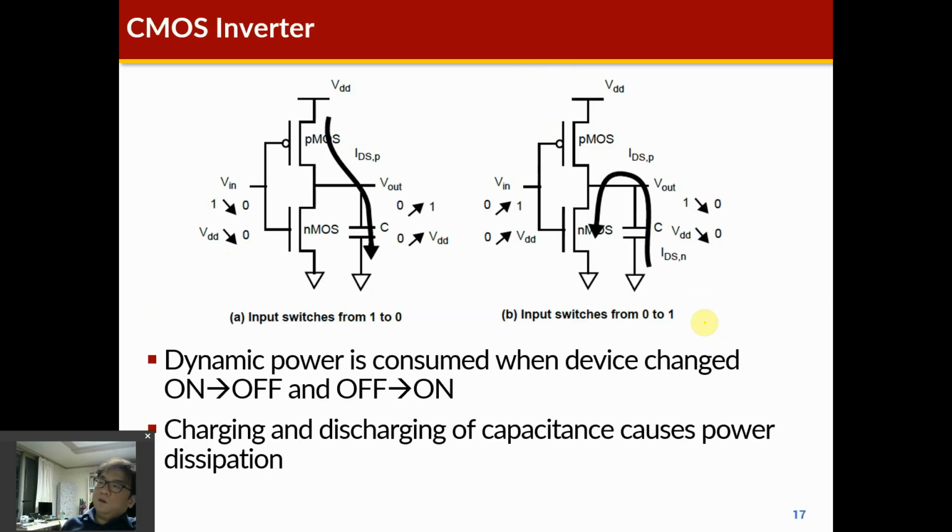So this is the CMOS inverter, the logic circuit of the CMOS inverter. And as I explained, you can think that this CMOS transistor is the voltage controlled switch. A CMOS circuit is composed of PMOS and nMOS, and one of these MOS transistors is on and the other off during the operation. So in this case, the V in is actually 0.